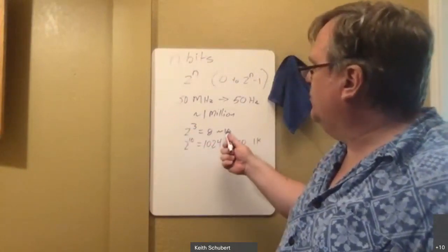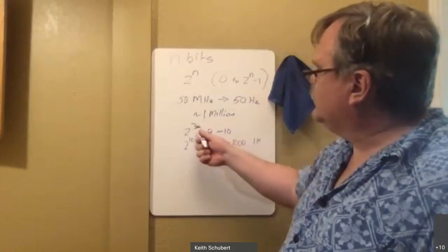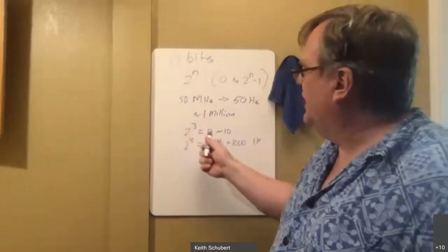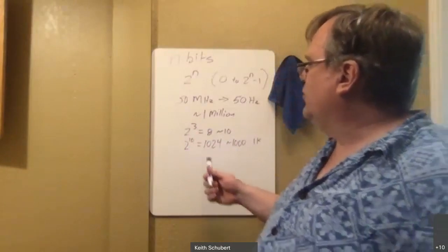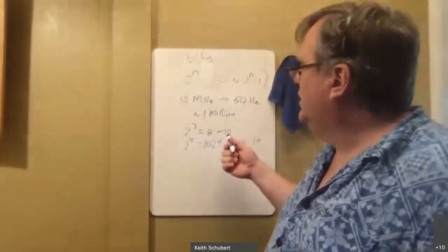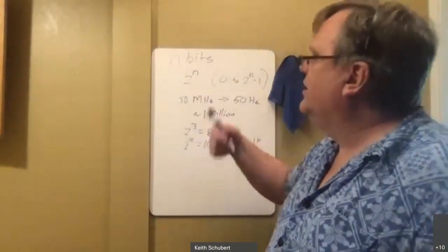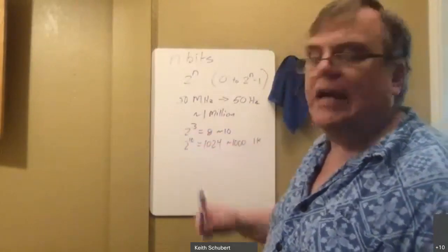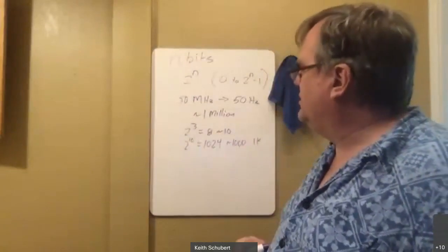So every time we have something that's a multiple of 1,000, I know I need 10 bits basically. If I break things down into multiples of 10, I need at least 3 bits. So you'll see this as a slight underestimation. So on these we'll often calculate based on this, and then add 1 extra bit to account for the fact that we undersized it. So for instance, 10 cubed is 1,000. So I could say, okay, I need 3 of these, which is 9. Count 1 extra bit for safety because I was undersized. So that gives me 10, which is exactly what my approximation here is. So that's basically why the ballpark works.